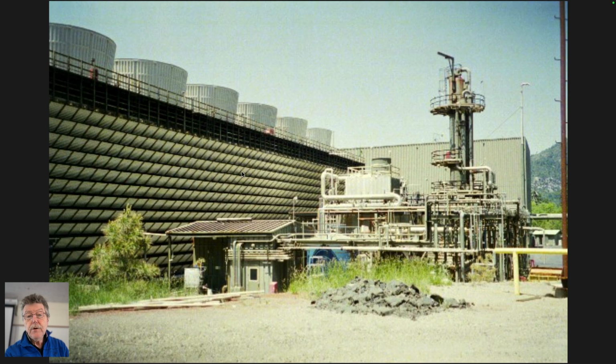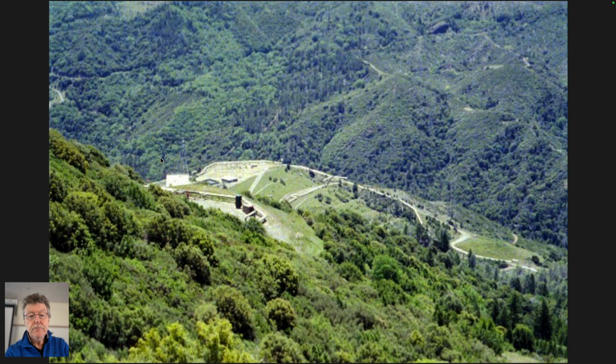Just as we saw at Rotokawa in New Zealand, a condenser, the spent fluids as they've gone through the turbine are exhausted into a condenser. They circulate in a big radiator. It's not a geological radiator, a mechanical radiator with air being circulated through it to cool it. You can only cool it as much as the ambient air temperature, which in this part of California would be maybe 25 degrees centigrade on average, and then condense the water and send it back to be re-injected. So close to Napa Valley,